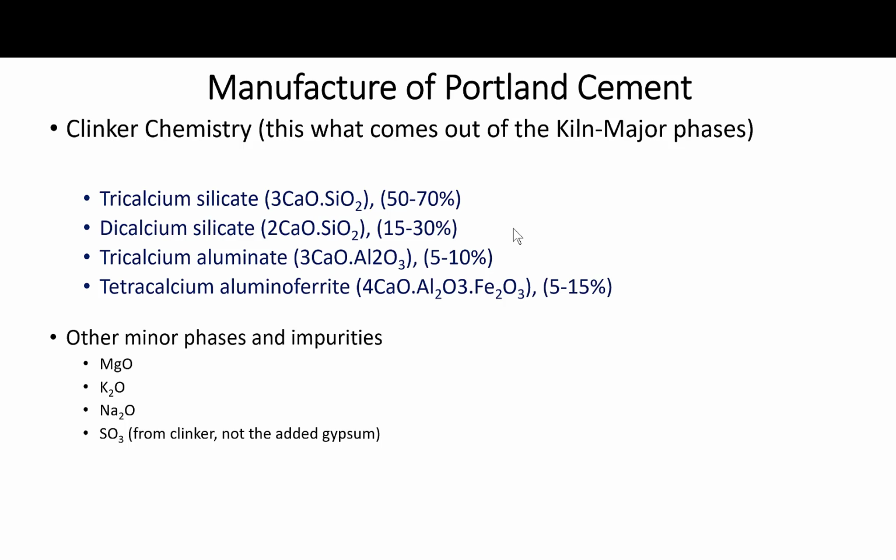However, the aluminum and iron are present in the silicate-bearing raw materials, the clays, and one benefit we get from these elements is that they work as fluxing agents, meaning they reduce the energy requirements inside the kiln. So they facilitate the formation of calcium silicate phases at a lower temperature than would otherwise be possible without their presence.